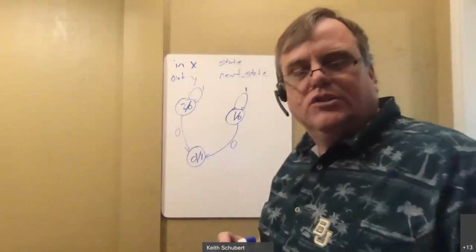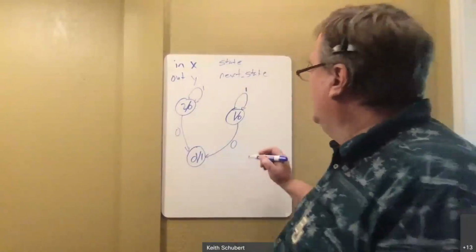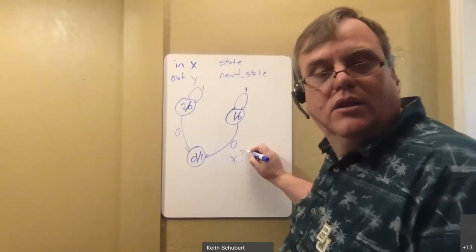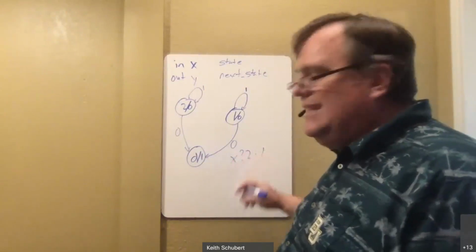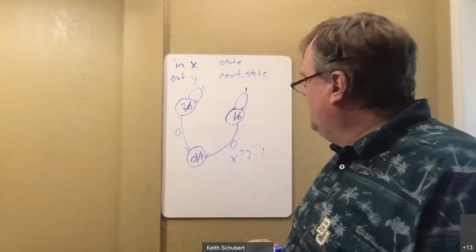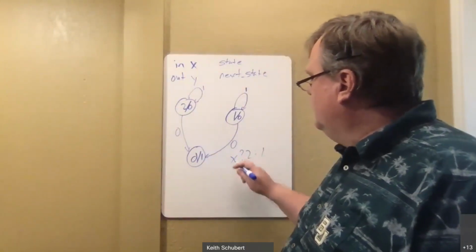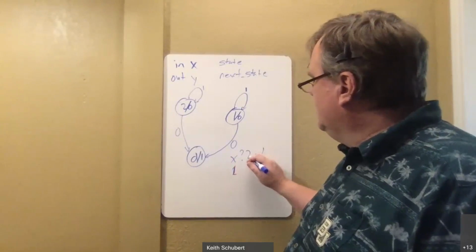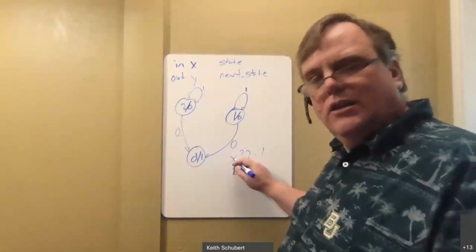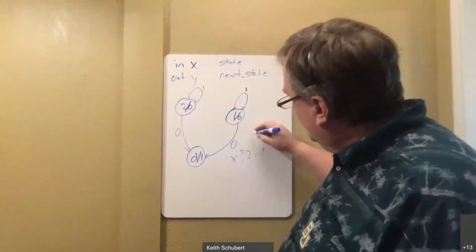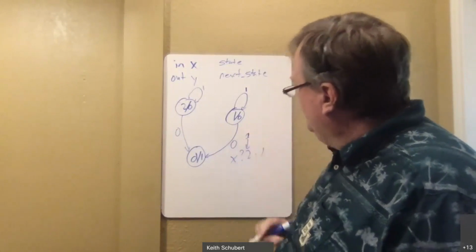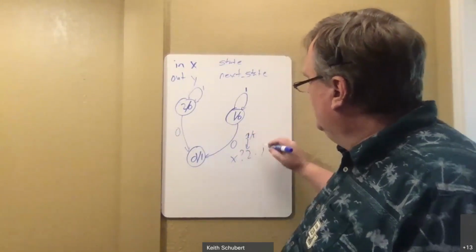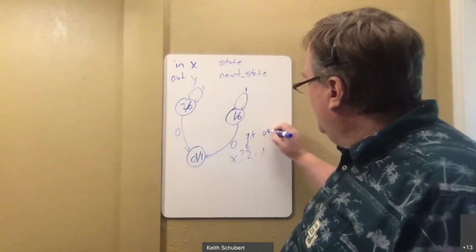Now, remember, default has this question colon. Question, and then 2 colon 1. So this notation is going to let one of my 2 outputs through, depending on what the state of x is. So if x is a 1, it lets the first one through, because this is saying x, is it true? So maybe I should label it better here. If x is 1, then you give this output. So this is the true. X is a 1 or true. If x is a 0 or false, it does the second one.